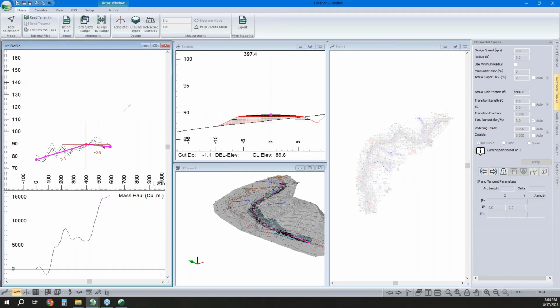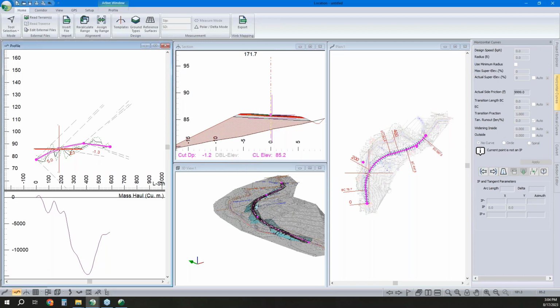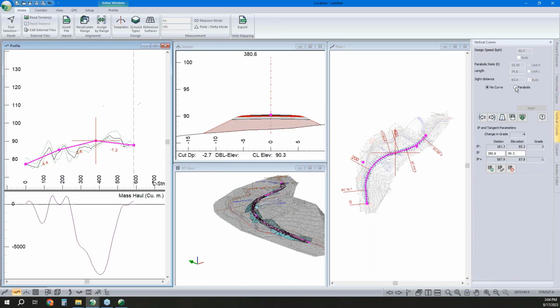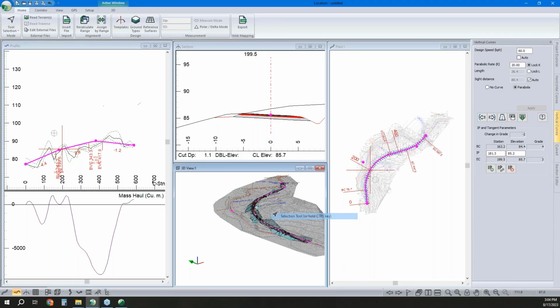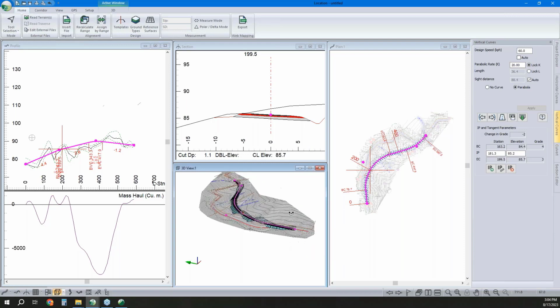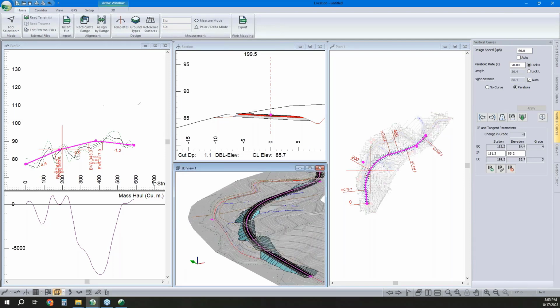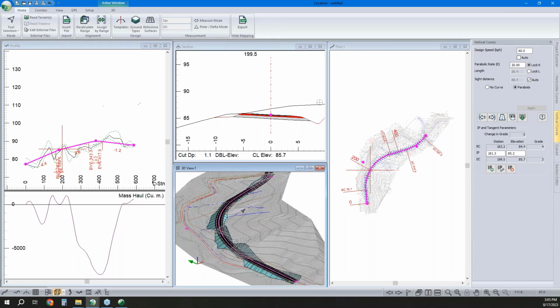So we've got that. Down here we've got our mass haul, and we'll be talking a bunch about that later. We'll try and get close to balancing. I'll throw some vertical curves in there. So, very close to balancing. I've got my 3D so we can see the surface that we're working with. So I've figured out a road design. If it was real, not just rushing through it, I'd spend a little more time on the details, but that is the gist of it.